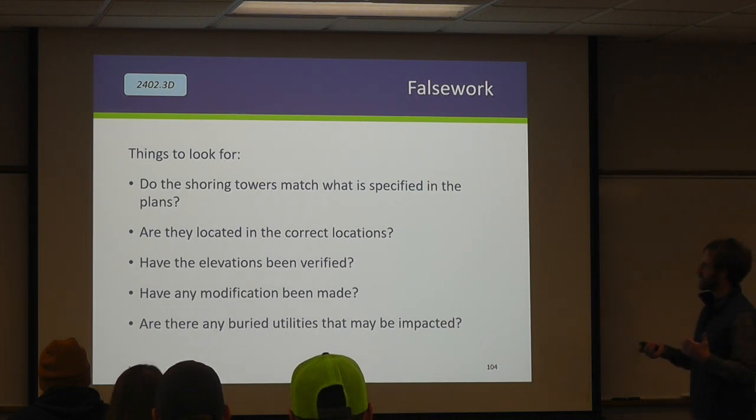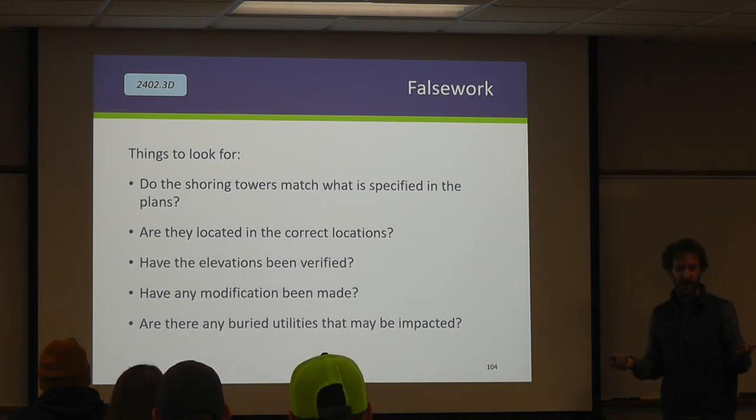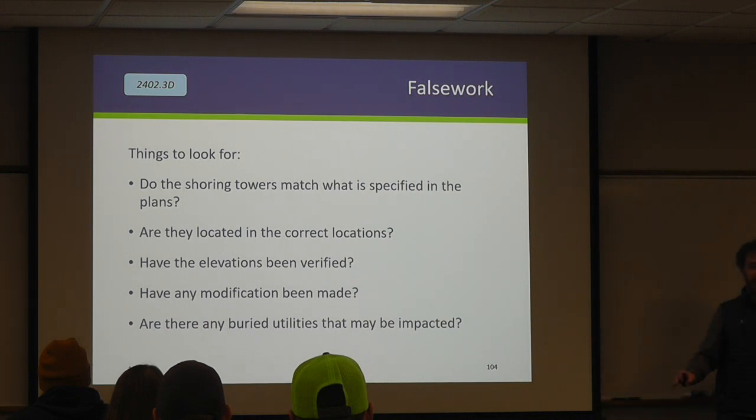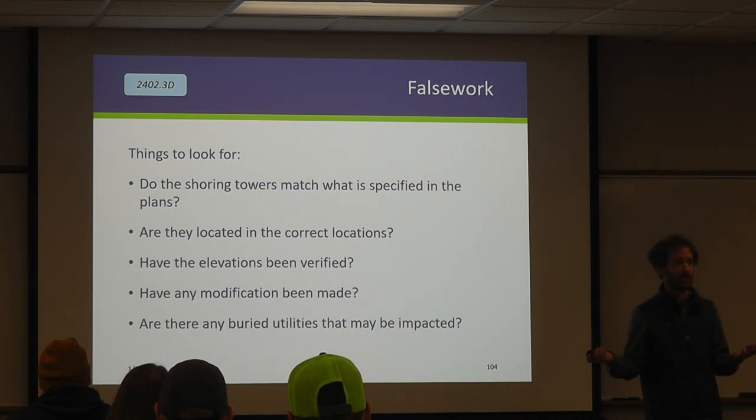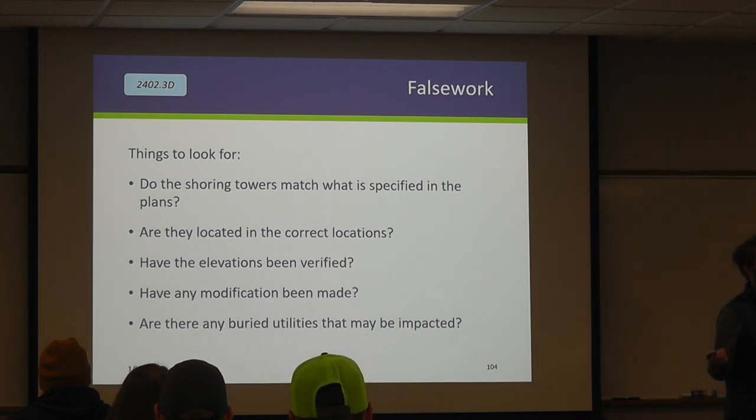Has the elevation been verified? Again, that's on the contractor. Did they modify it? Did they cut a leg off the shoring tower? Does that seem like a good idea? Has it been like that all along? Right. Are there any buried utilities? We almost crushed a 72-inch pipe because the contractor didn't locate the utilities ahead of time. That would probably have been bad, not only for the utility, but the steel would have dropped too, right?